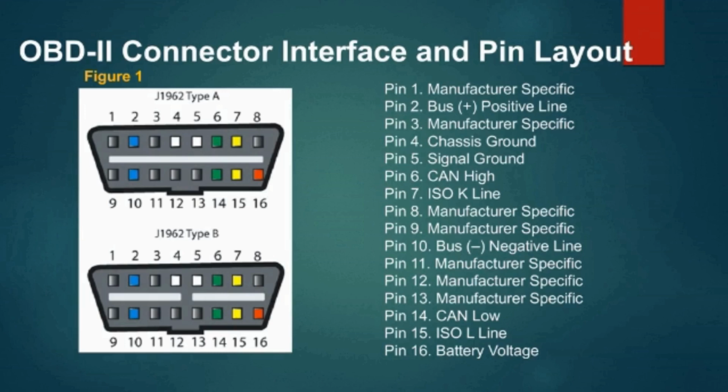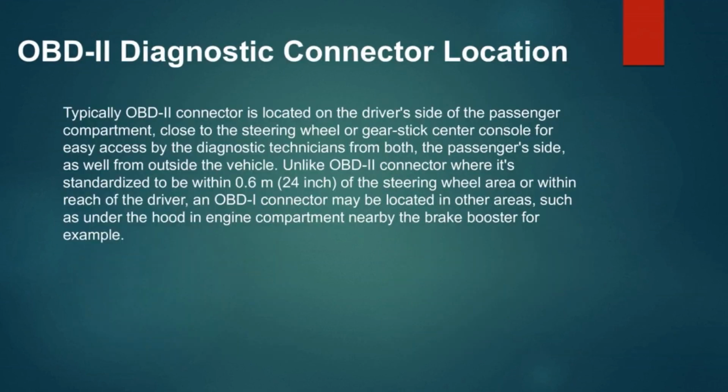Pin 8, manufacturer-specific. Pin 9, manufacturer-specific. Pin 10, bus minus, negative line. Pin 11, manufacturer-specific. Pin 12, manufacturer-specific. Pin 13, manufacturer-specific. Pin 14, CAN low. Pin 15, ISO L line. Pin 16, battery voltage.